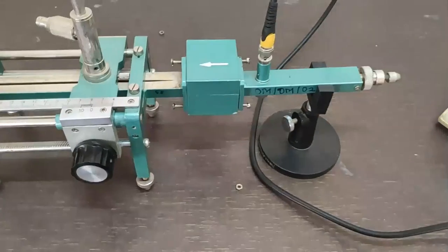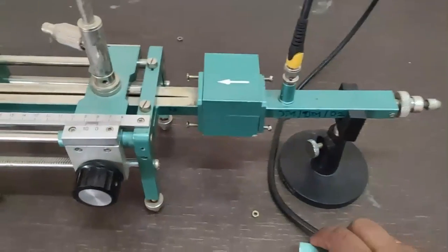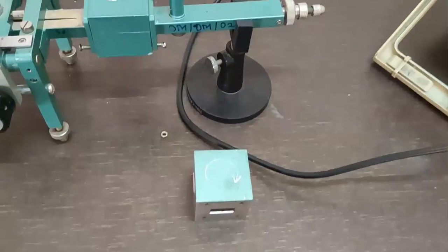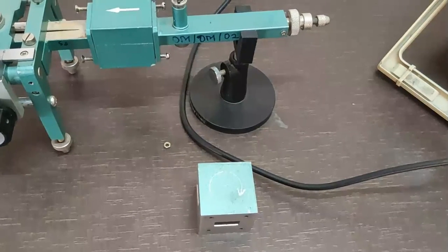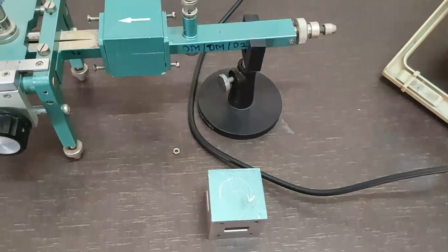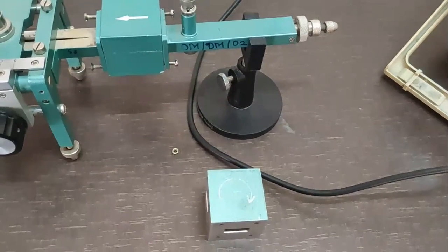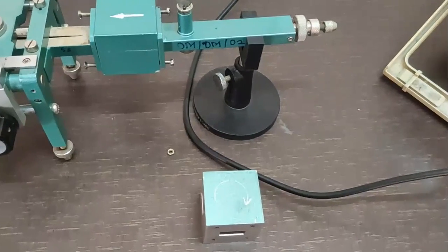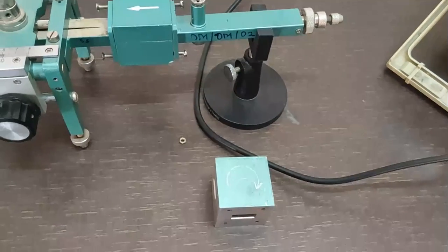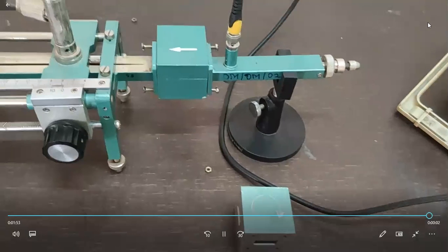The same procedure you can apply for the circulator, and only for the circulator you have to find VSWR for ports number 1, 2 and 3. For finding insertion loss you need V1 and V2. V1 is before insertion of the circulator and V2 is after insertion of the circulator. In this way you can perform port characteristics of the isolator and circulator.